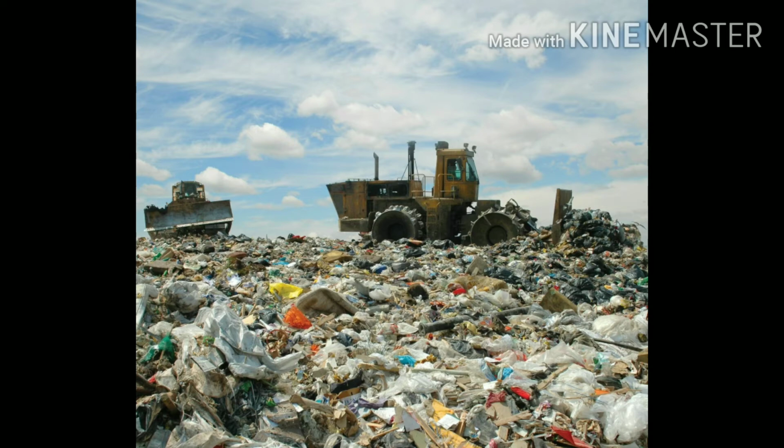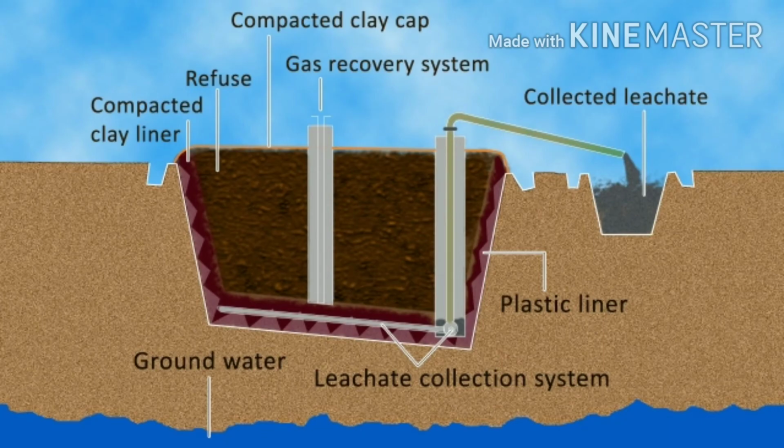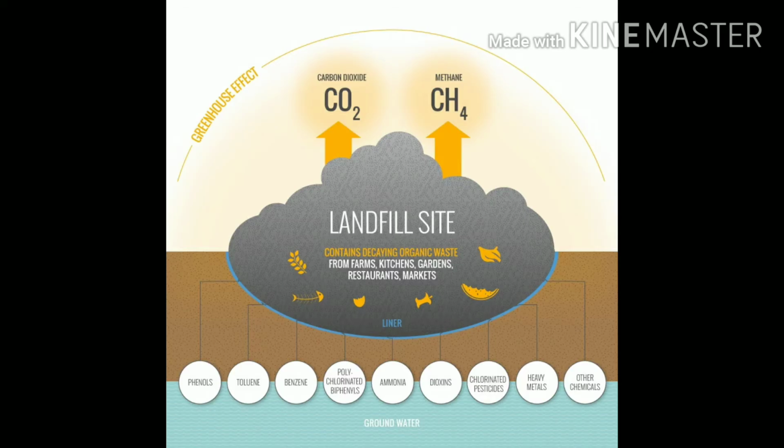A method of waste disposal on land without destroying the environment or creating nuisance or health hazards to the residents, but using principles of technology and keeping the volume of refuse to the minimum, is called landfilling. To prevent insects or rodents from entering the landfills, the dumping area is covered with layers of earth. The waste gets decomposed by physical, chemical and biological reactions, producing different gases like carbon dioxide, methane, ammonia and hydrogen sulfide.